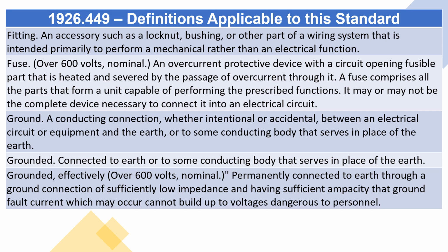Fuse. Over 600 volts, nominal. An overcurrent protective device with a circuit opening fusible part that is heated and severed by the passage of overcurrent through it. A fuse comprises all the parts that form a unit capable of performing the prescribed functions. It may or may not be the complete device necessary to connect it into an electrical circuit.